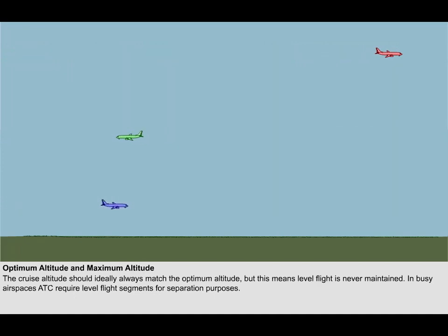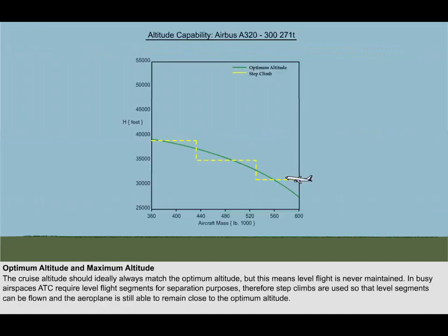Aircraft must fly by segments of constant altitude, which must be as close as possible to the optimum altitude. The level segments are established within 2,000 feet of the optimum altitude. Remaining within 2,000 feet of the optimum altitude ensures the range is 99% of the maximum specific range.